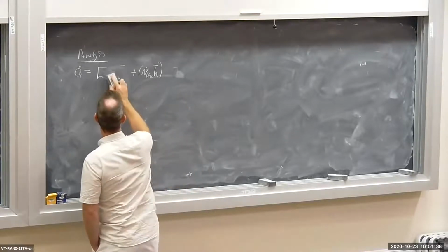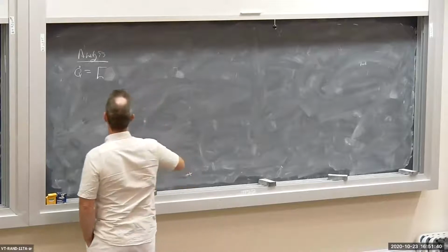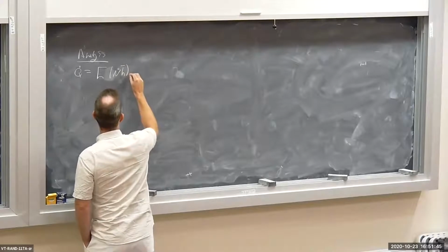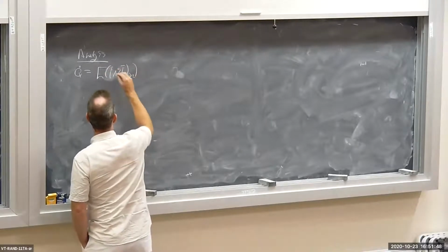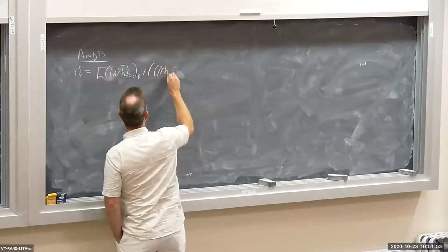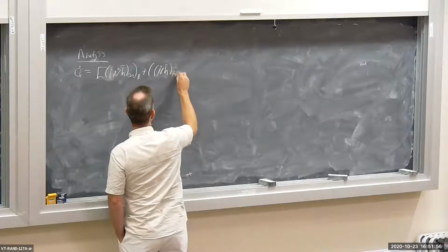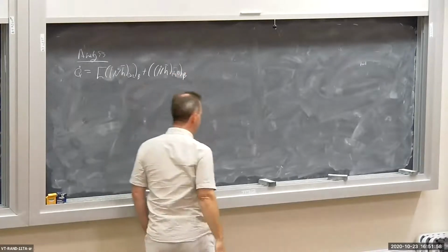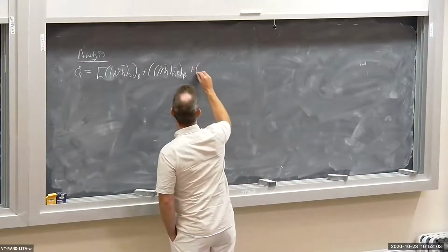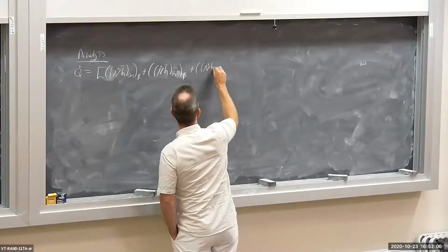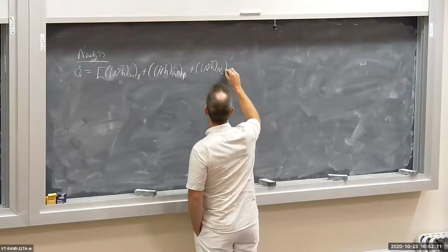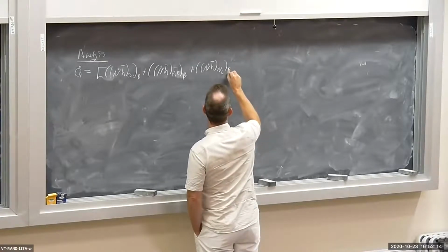Make sure my notation's a little bit better here. So N dot H bar, and that's going to be for the CO2 at the outlet or the product side. And then I have N dot H bar for the H2O evaluated at the outlet. That's on the product side. And then I have plus N dot H bar for the nitrogen, which doesn't participate in the reaction, so it doesn't get burned up. And that is evaluated at the outlet as well.